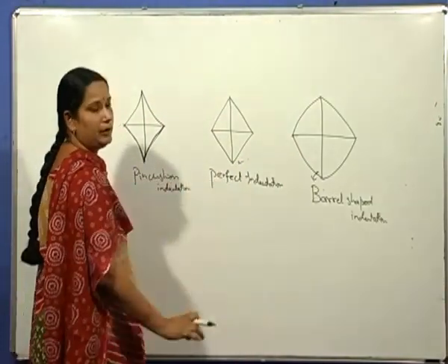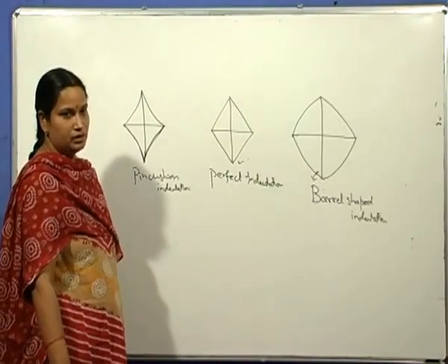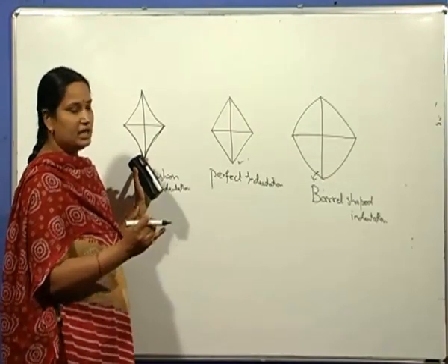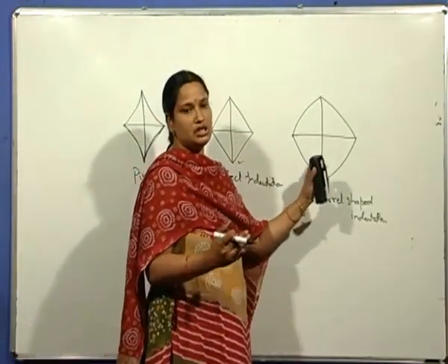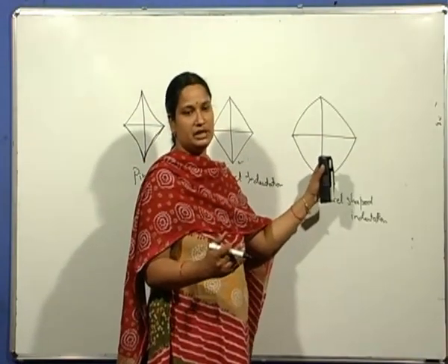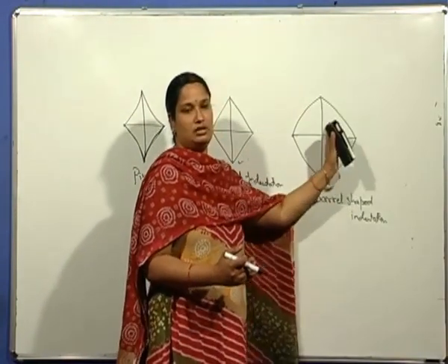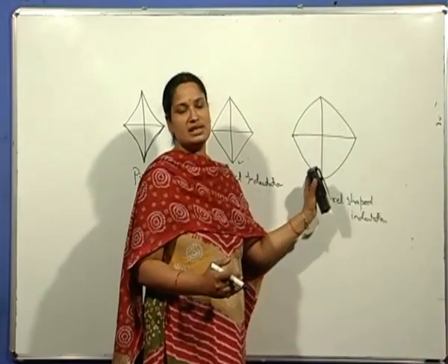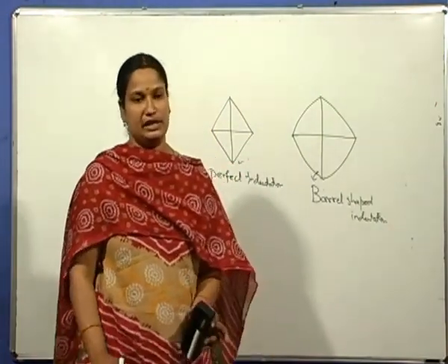This is due to the sinking of the material in one case, and the ridging up or piling up of material in the other, which results in an increase in surface area of the indentation.